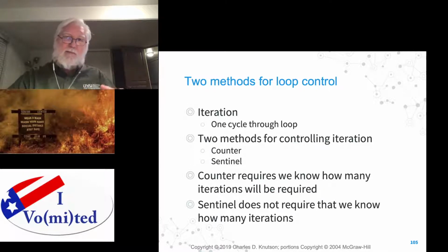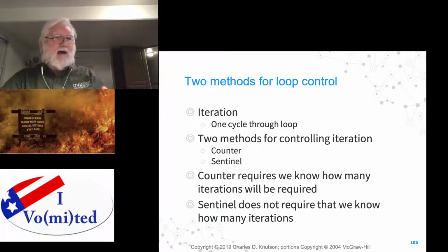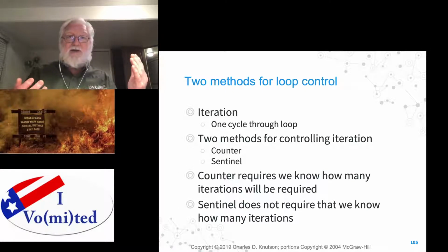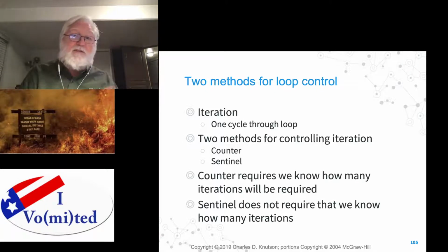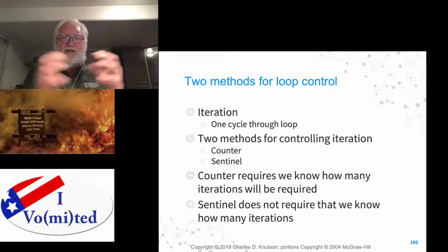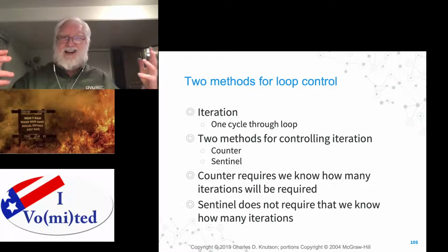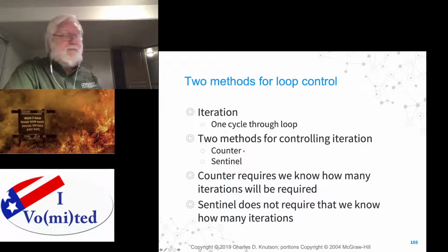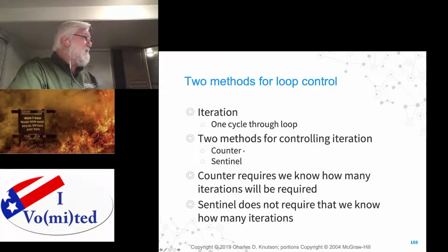You could count up to a certain value, like I'm going to count up to 50, and then to check it, there's no check to say when it gets to be 50, then stop. But I could do something like take that value, add it to negative 50, and when that result is 0, then I'm done. I could do other tricks. But mostly, it's easiest in assembly language to count down.